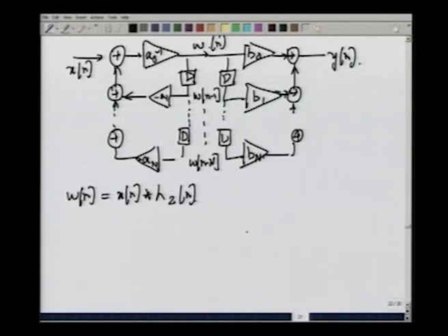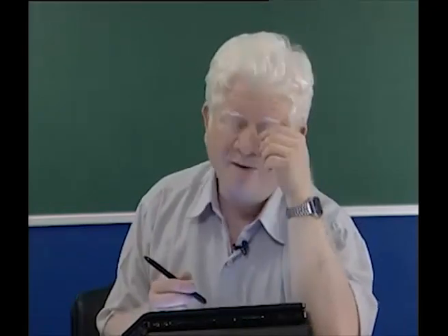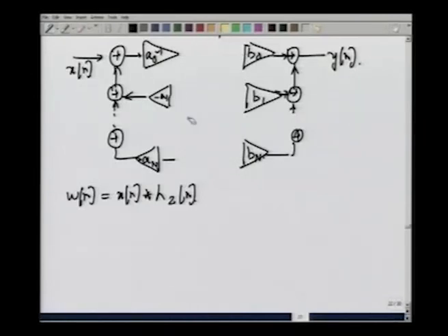So let us just knock off 2 parallel sets of delay blocks and replace it by one set of delay blocks. So I am going to do that by removing these parts and putting a single signal which directly goes in over here. This gets delayed by 1 time.